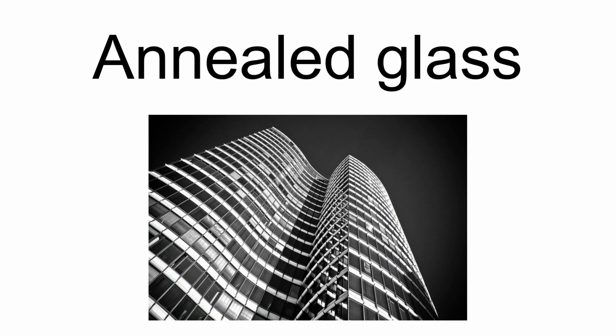Annealed glass is glass without internal stresses caused by heat treatment, i.e., rapid cooling, or by toughening or heat strengthening. Glass becomes annealed if it is heated above a transition point, then allowed to cool slowly, without being quenched. Float glass is annealed during the process of manufacture. However, most toughened glass is made from float glass that has been specially heat treated.